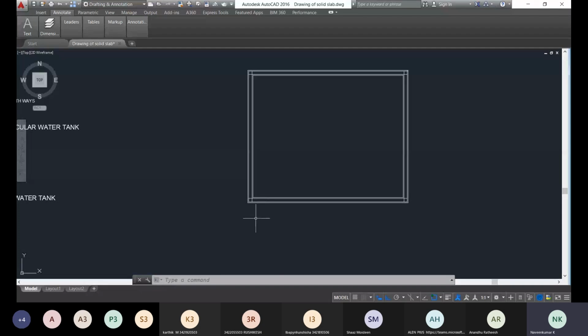We are going to provide the distribution bar. Okay, so before going into the distribution reinforcement, in circular tanks that portion is not there, but in a rectangular water tank, additionally one provision is there. That provision is called haunch. At the corner, there is a sloped structure. If you have seen a rectangular shaped water tank, at the corner there will be a slope as well as at the top also, if it is a closed water tank. So at the base, there will be